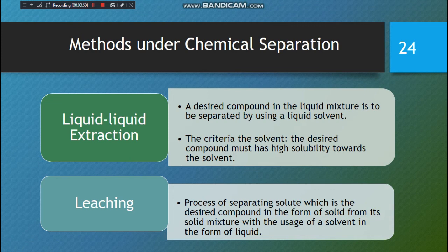And sometimes we define LLE, or liquid-liquid extraction, as a solution containing the desired component A and solvent C mixed with another liquid B. So a fraction of A is then extracted from C into B. However, B cannot be completely miscible with C. The greater the immiscibility between B and C, the better the process. So the B-rich phase containing A has to be easier to separate than the C-rich phase. Otherwise, the whole extraction scheme becomes unnecessary.